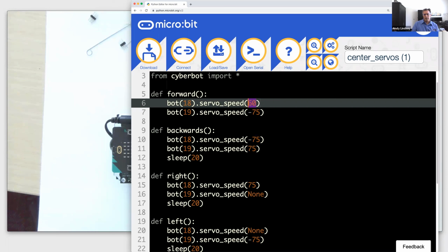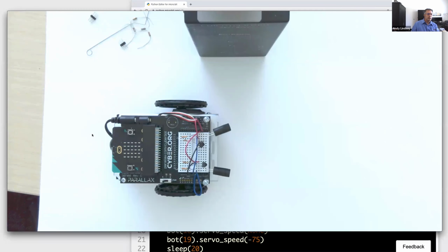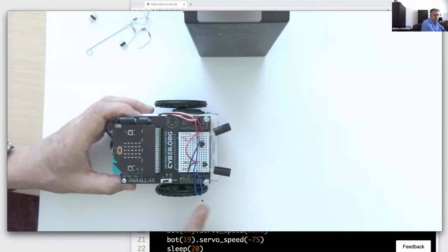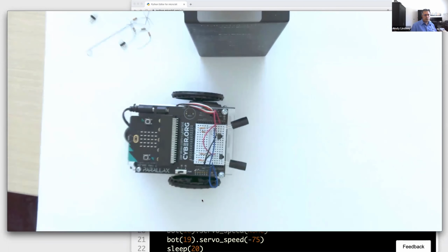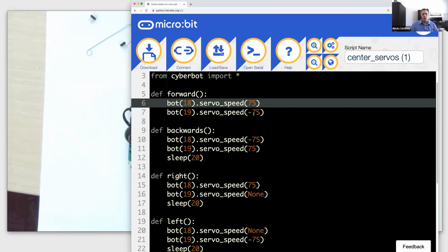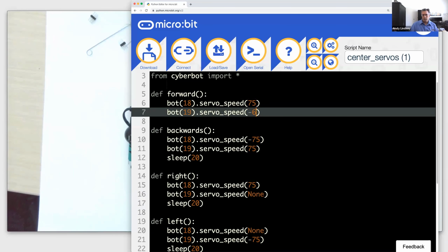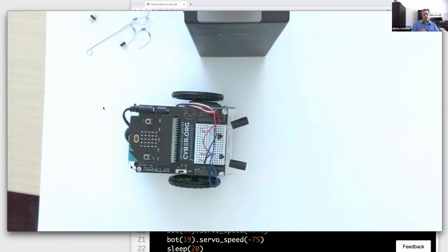And then if it's curving to the left, that would mean that this right wheel is turning faster. So you'd want to instead reduce the right wheel speed. And 60 would be like a hunt and peck thing, and you'll probably need to try a couple times until you get it dialed in. And that's something that we'll want your students to do too.